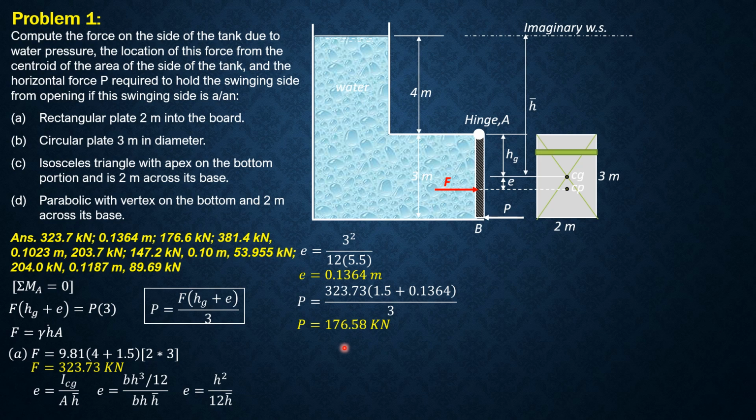Now by integration, we consider a strip, a horizontal strip, where the constant pressure is acting. So we have this dimension y, dy. So this is dF, and dF is gamma or 9.81, then the distance of the centroid to the imaginary surface is h, or y in general, and that is 7 minus y because we denoted this by y.